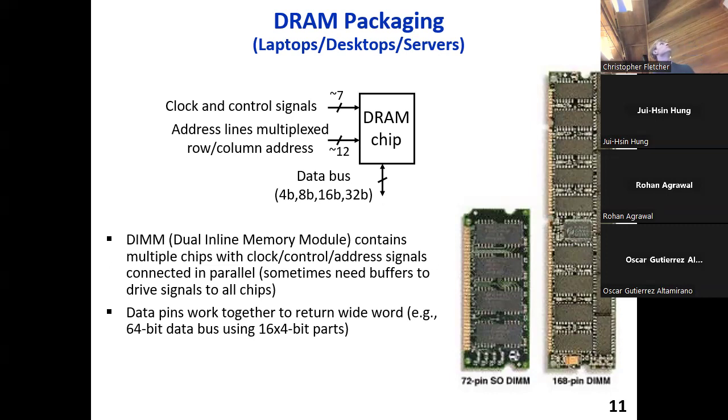What they will also do is, instead of just having a wide address bus where your entire address, let's call it the n plus m bits, are in n plus m wires, with all the wires there at one time that you can just pass your address to, which is the way that you think about accessing a RAM, the way it's organized in DRAM is that it's temporally multiplexed and serialized over fewer wires.